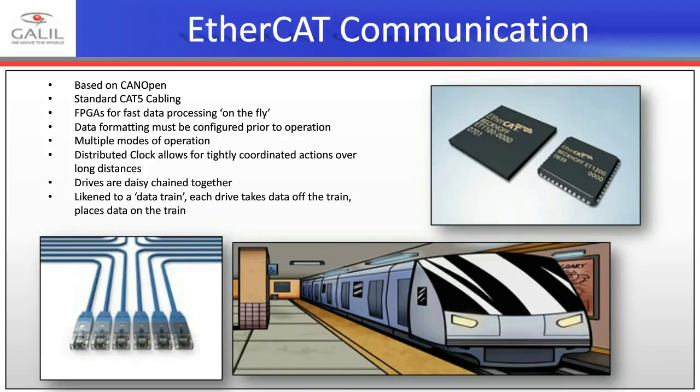In a motion control context, what is the data that's being sent over EtherCAT? You're seeing data specifically sent from a motion control master to, say, an EtherCAT drive, so an amplifier and motor, and you're specifically sending position, velocity, or torque information to that drive. And for I/O modules, you're looking at digital or analog input and output.